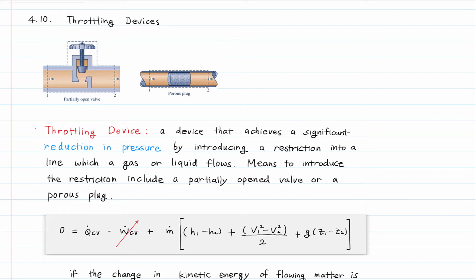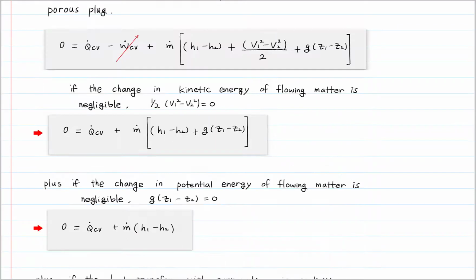When a liquid refrigerant passes through a throttling device, the pressure is reduced, and the refrigerant evaporates at a low temperature. A throttling device can be analyzed under steady operating conditions. It does not involve any work other than flow work of the flowing streams.